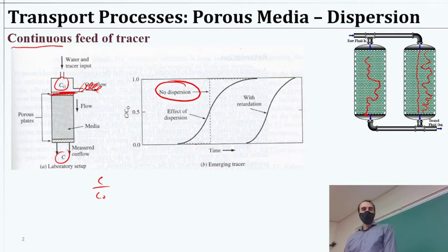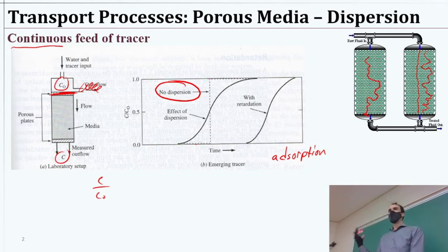Okay, so that's dispersion, and then this retardation part, really that's generally caused by adsorption, which is another process that sometimes we'll use intentionally for treatment. Activated carbon, if you've ever used a Brita filter at home, essentially what you're doing is an adsorption process. Whatever molecules might be hanging around in the water, you're wanting them to stick onto the surface here, and while they might one day eventually come back out, especially if you saturate it, the idea is it's got a lot of space, that activated carbon stuff, a lot of space for molecules to stick to it, and we'll remove it that way. And then you could replace it every once in a while, and you'd be good.